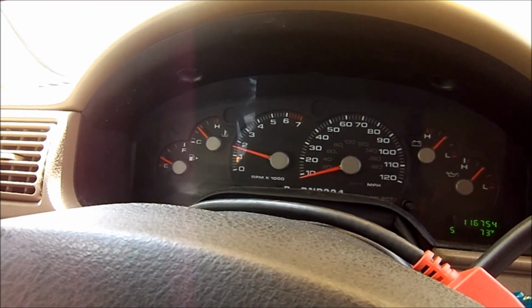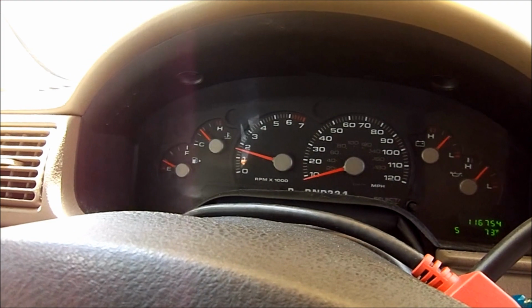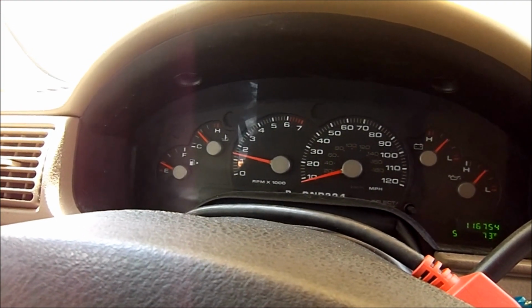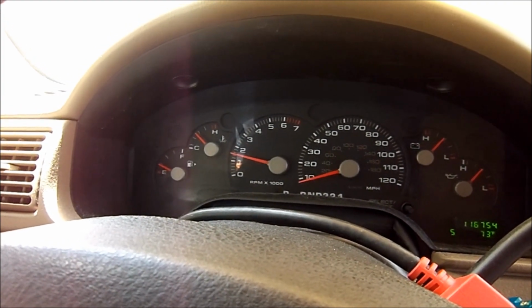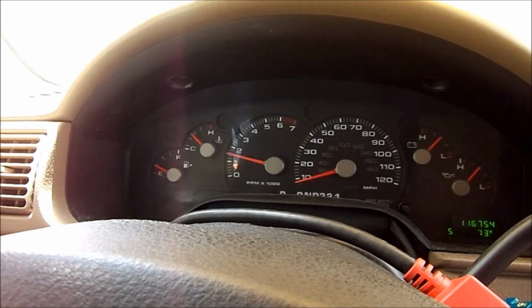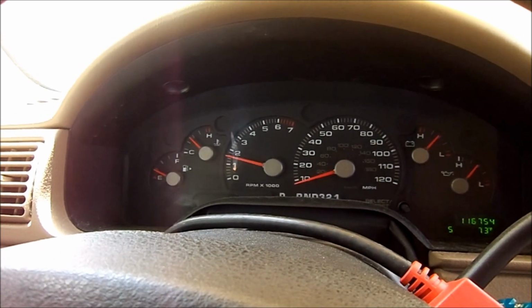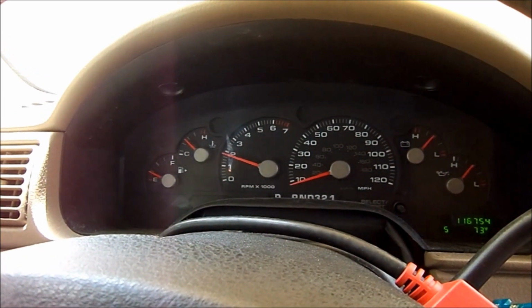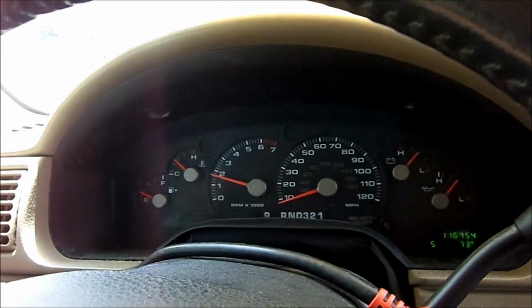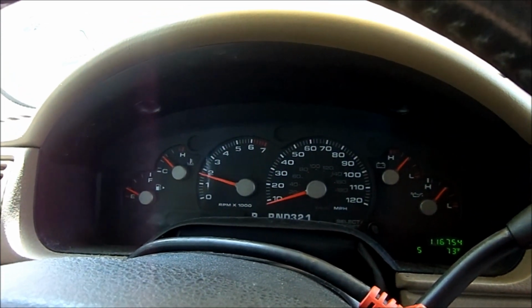We are at about 1600 RPM, and right now it's checking all the sensors. The RPM drop is kind of misfiring. It's probably checking the injectors, turning them off one by one and just looking for an RPM drop. This is the key on engine running test,